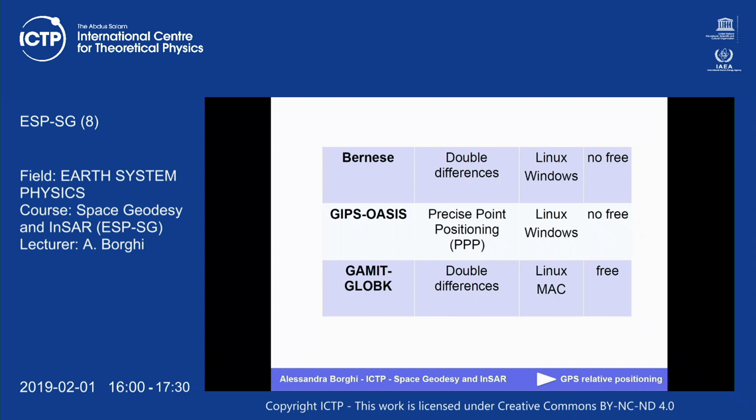But now with precise point positioning, you don't need relative positioning, so you don't need to connect a station with baselines. Now we have a lot of global models about ionosphere delay, troposphere delay, and so on, so you can correct your data using these models. We have really improved our capability in precise point positioning.